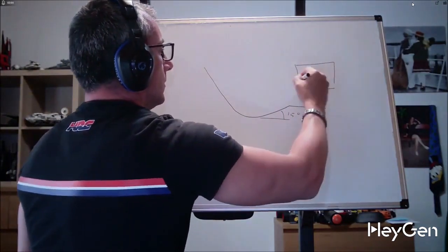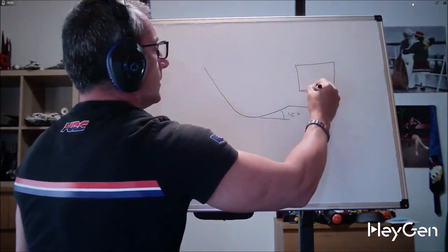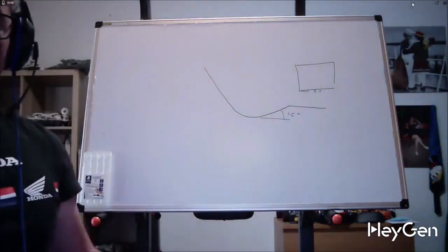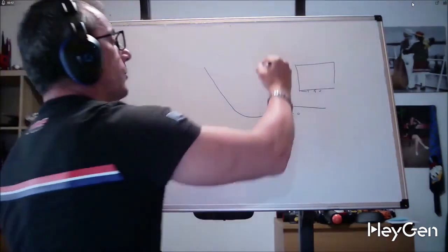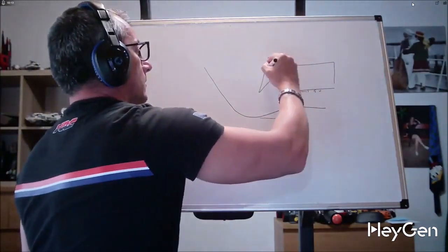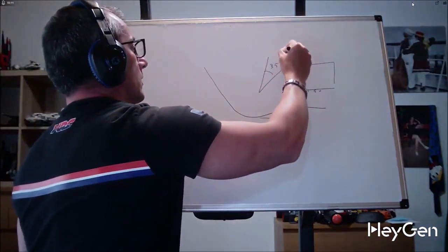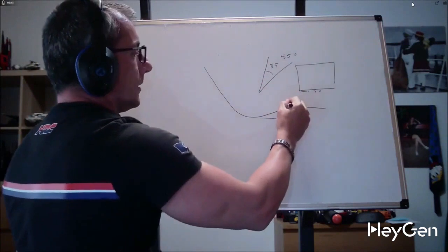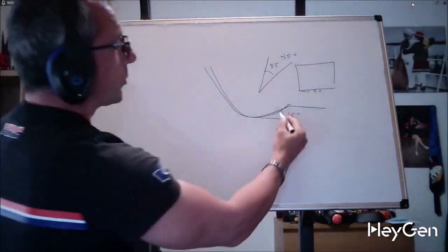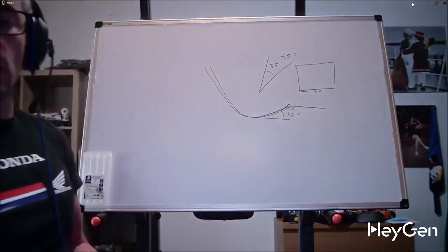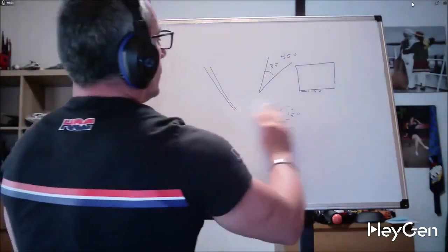No, I will never be able to do it. So I will have to use, for example, a tool with 35 degrees or 55 degrees, which allows descending without working from the back, thus without removing more material in this area.